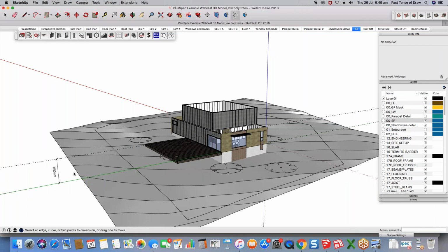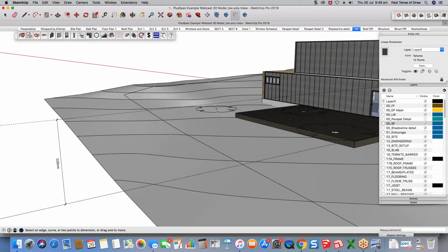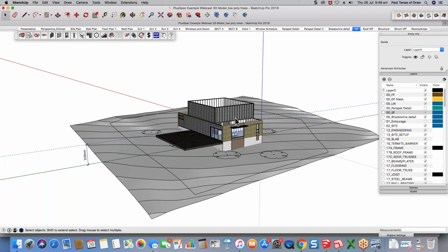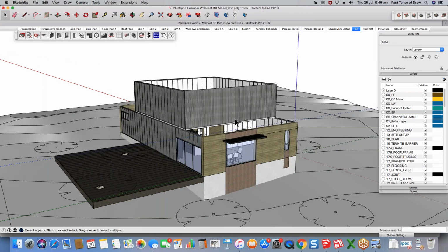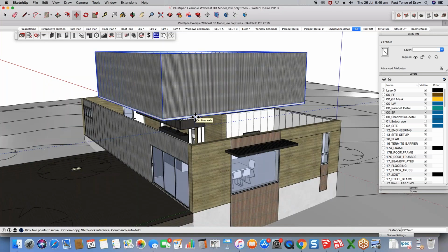So I now know what my dimension is. Now, the question is, if I move that, what I do, like I showed you before, is I left click on the guide which is for that level, and then I select my new level, and I might know that I actually need to raise it by 3 feet. Type in 3 feet, I've raised it, and you can see that my guide has gone with it, and my dimensions have automatically been updated.